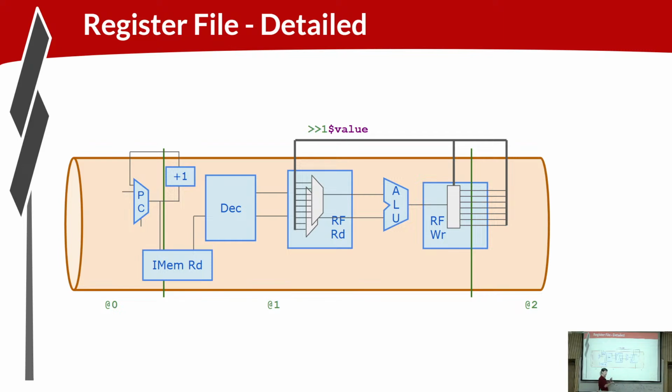Mapping it out this way, it looks a little bit uglier as a logic diagram, but it's organized very clearly what's being done at each stage by a particular instruction. So it's very clear when you map it out this way that the data that you're reading is the data that was updated by the instruction before because of this one cycle loop.